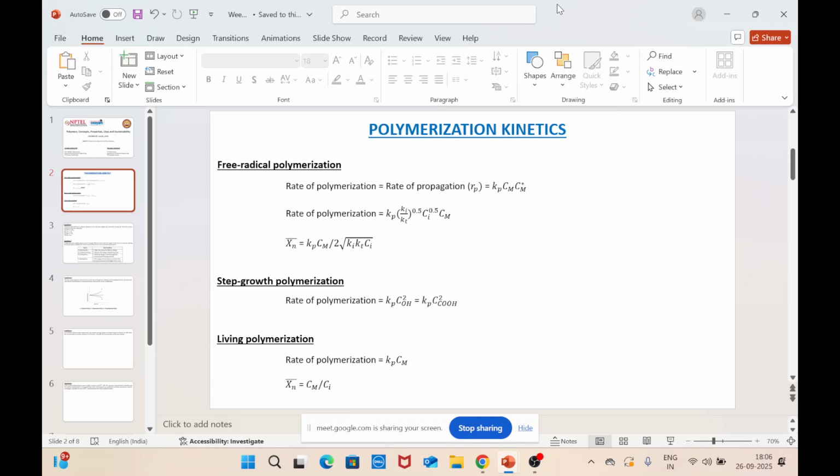Similarly, there is also pressure. If you have a very high pressure, then the polymer melt can overflow through the mold, and in case of low pressure, there is a possibility of significant shrinkage in the polymer product. So all these process parameters need to be optimized. They cannot remain very high or very low. They need to be optimized so that we can achieve our desired product.